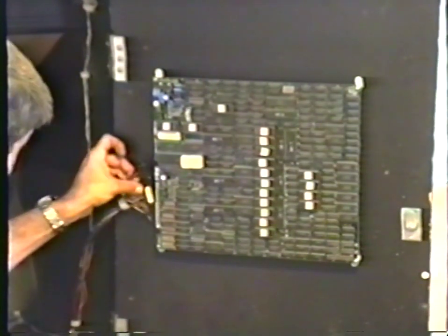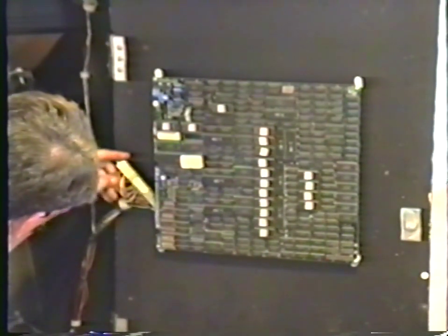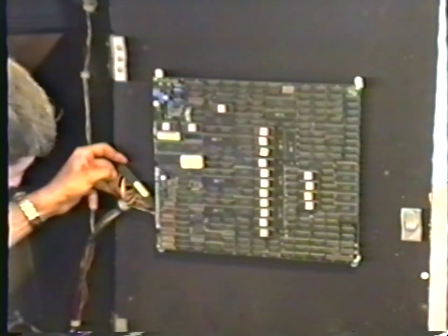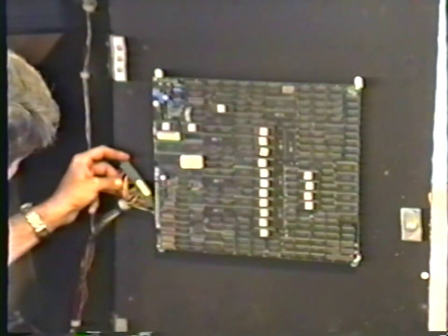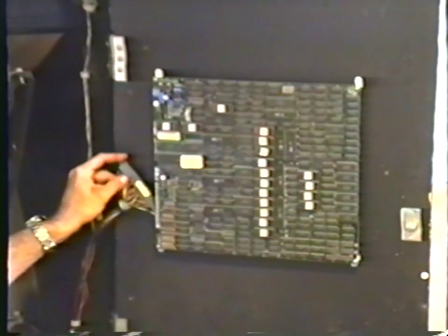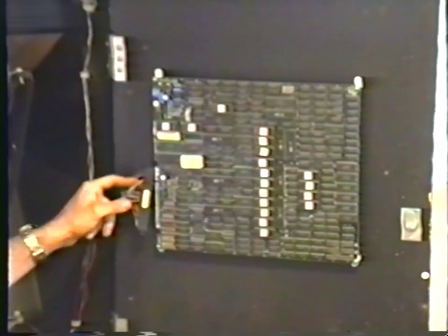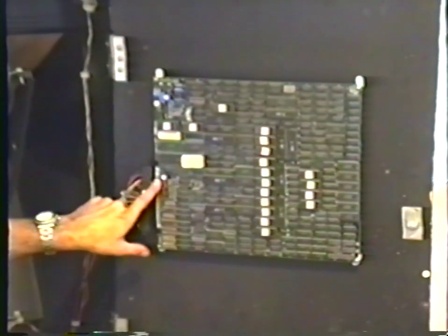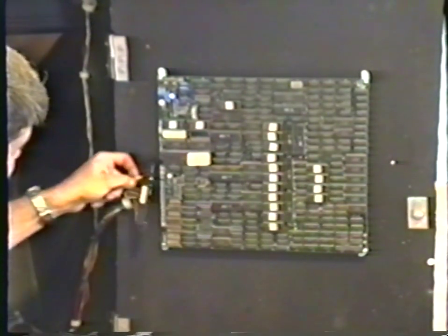You may find that the minus 5 volts is unused in some games. It apparently is not used in this game because I have the ground wires, they're black. I have the red wires, that's for the plus 5. Then there's a blank spot right here. Pins 5 and E are not used. So this game doesn't use the minus 5. If you have a standard connector with minus 5 hooked up, and the board doesn't use it, that's okay. It's just not hooked up to anything. On the board here, there's a little pin, but it's just not used. And then the yellow wires for the plus 12.